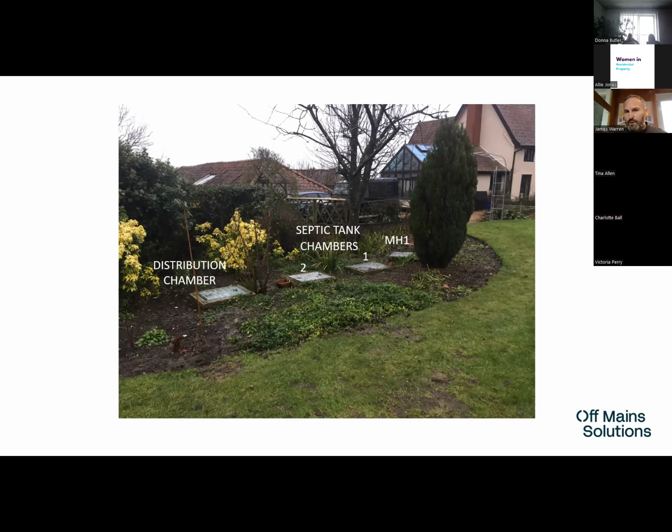If you lift the covers for the 2 septic tank chambers and look down, you shouldn't really see anything. And bear with me, because I know that sounds a bit odd, but if that septic tank is performing well, it should have formed that crust. I know it's disgusting, what we talked about earlier. When you're looking at the top side of a crust, it looks like a concrete drive. So you can't really see much, but that's actually a massive thumbs up that that tank is performing well.